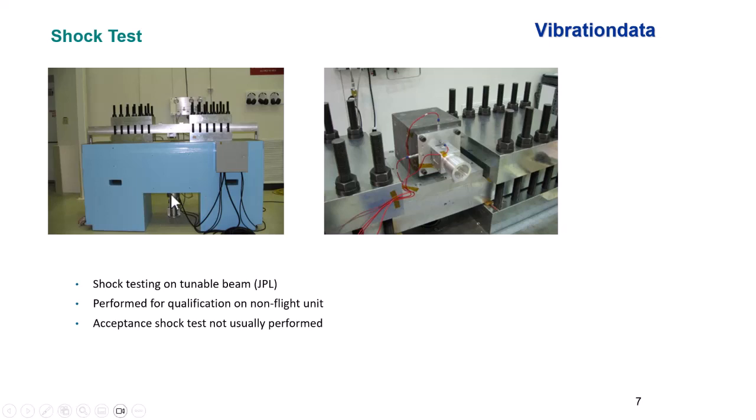Now on the underside, there's a cylindrical device, and that's actually an air gun, sometimes called a cannon. It's charged up with air pressure, and then the pressure is suddenly released, and it's going to drive a projectile to the underside of that beam. And that projectile, again, the test conductor can decide what type and size and mass of projectile to use, as well as what should be the initial pressure, in terms of potential energy of that air gun.